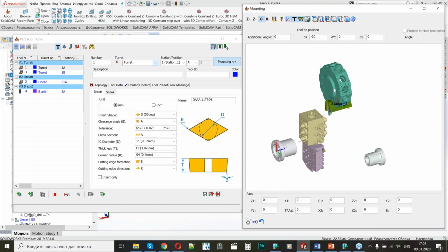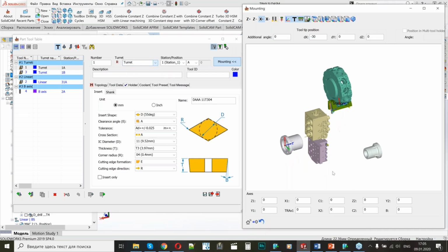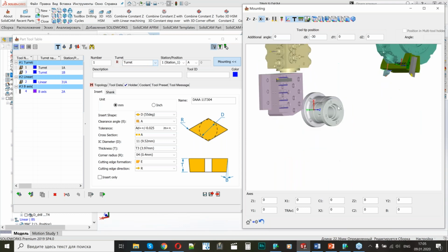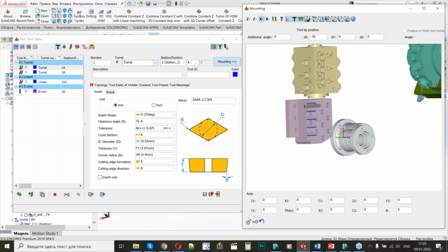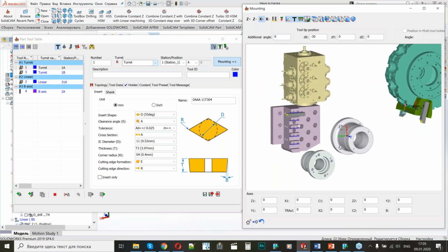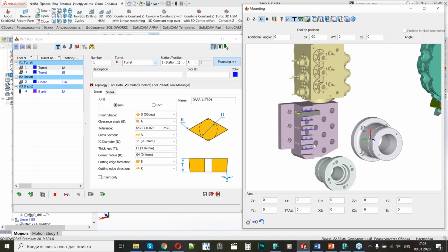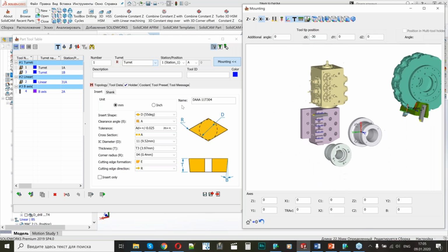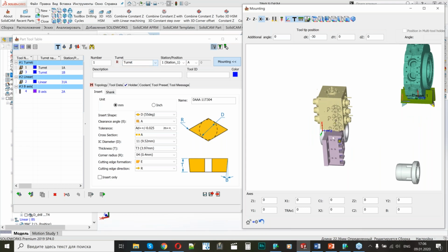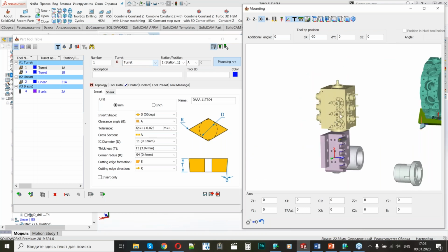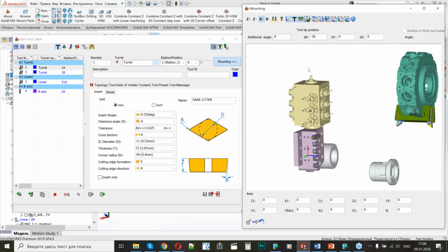It can be applied for both spindles. Also, I have the linear turret here. It's a lower turret in a gantry. It can provide the turning operations, OD and ID turning, and the most complex is the B-axis turret because it can rotate and provide a tool change during the rotation and during the moving by Y-axis.